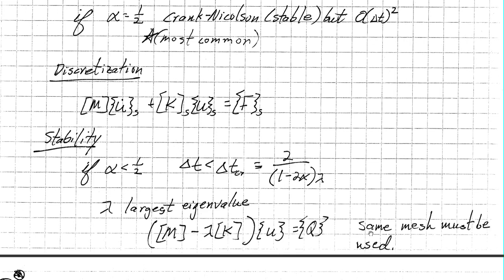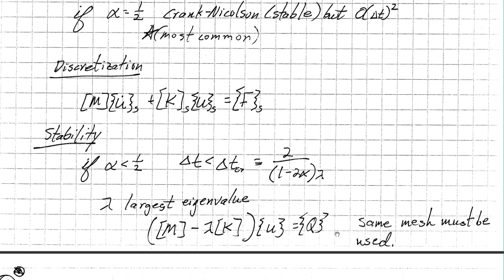And you have to be careful with the size of the mesh used. One thing to keep in mind on the size of these meshes is if you continue increasing your mesh density, you can resolve more modes, but usually these higher order modes become negligible in terms of the amount of energy they'll carry. Usually the first few modes are the ones that are most commonly seen in engineering structures. So an overkill on a large mesh is often not necessary.